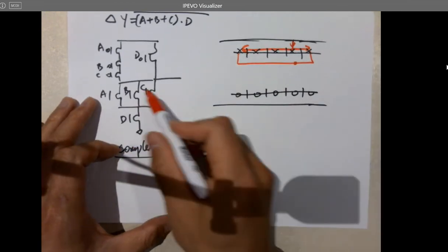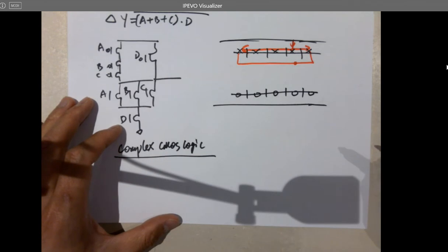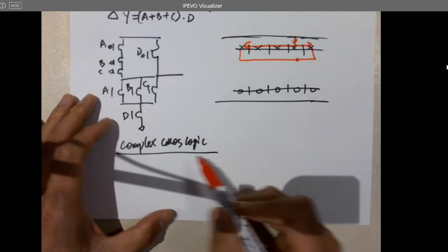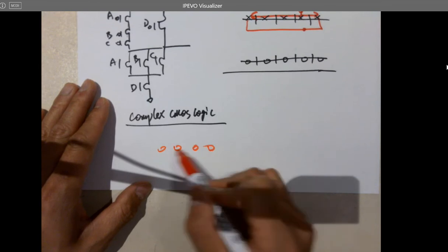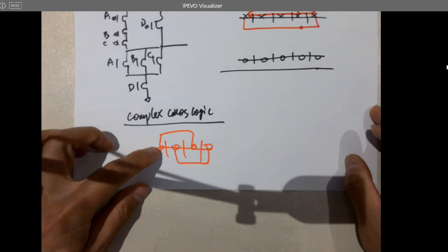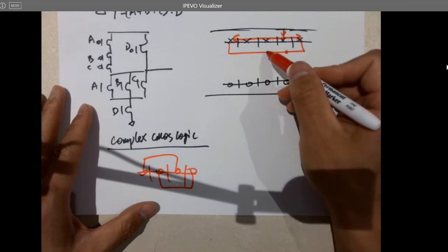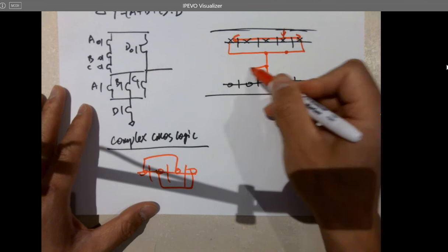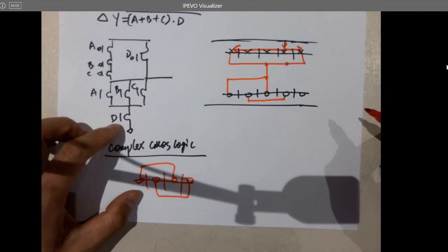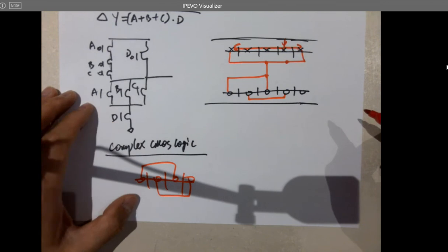And for these ones, 3 in parallel, 1 in series, how would you do it? Remember, 3 in parallel, we always have, remember how we do that? 3 in parallel, just this, right? That's 3 in parallel. So how can we do that? If I short this one to here, and I start that structure from here to here. So what about the last one? What about D? Can we still get this one in series with the parallel PMOSes?